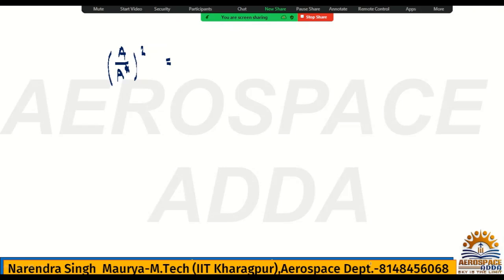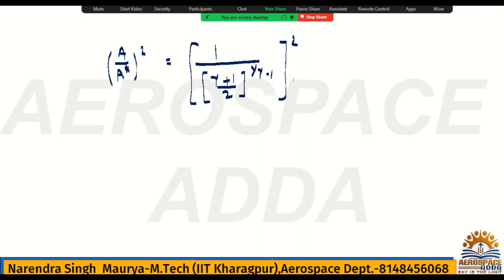So what we have, check rho star by rho naught. So rho star by rho naught will be 1 upon (gamma plus 1 by 2) to whole power 1 upon gamma minus 1. Okay, this is the rho star by rho naught, and we have a square, so we can keep a square here, into rho naught by rho.